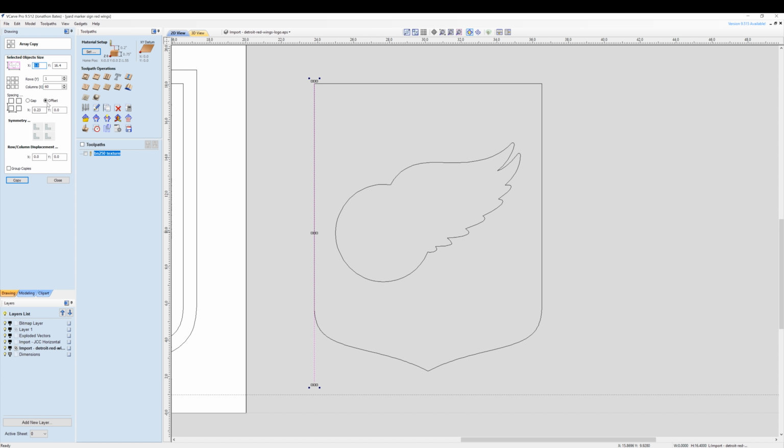So that's fine. We're going to use an offset of 0.23 for a 0.250 inch bit. And all of that looks good. I think 60 is going to be more than enough. Press copy. And there we go. 60 is more than enough.